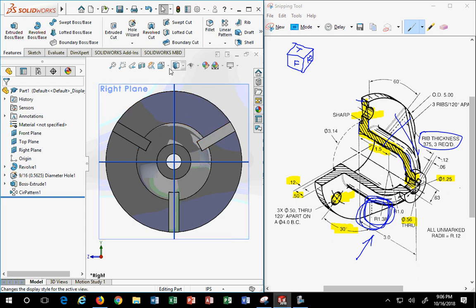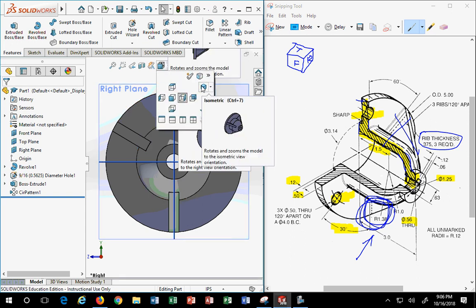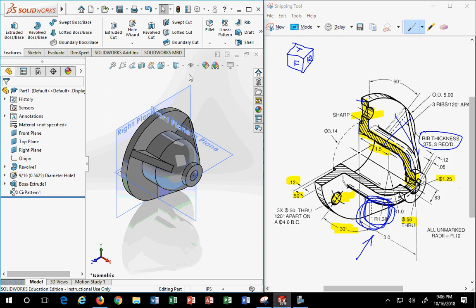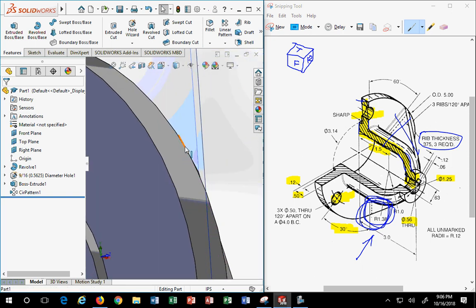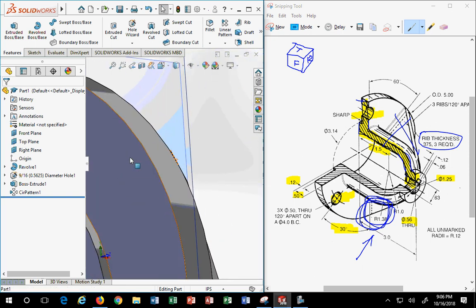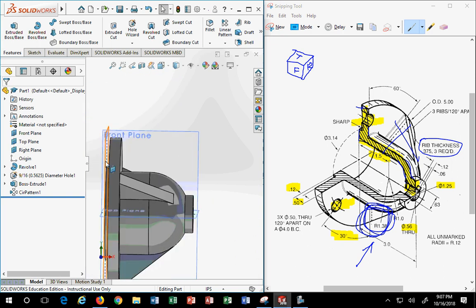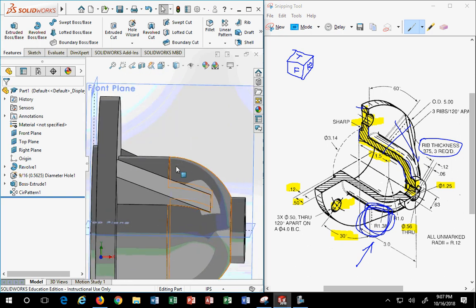The thing that makes us unique is trying to create that rib. And this is when I say, in the last project, what did we do? We just needed to pop off these corners, right? So we created a circle in the back and did an extrude opposite of a normal extrude cut. We inverted the extrude cut. We used it as a cookie cutter to keep everything inside of it. Remember that? When we did that project. So in this project, we're not going to leave this flat. We actually want this rounded.